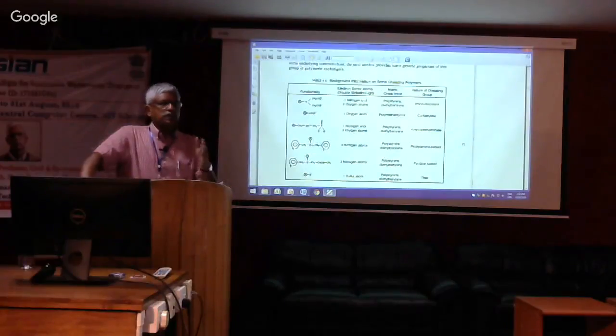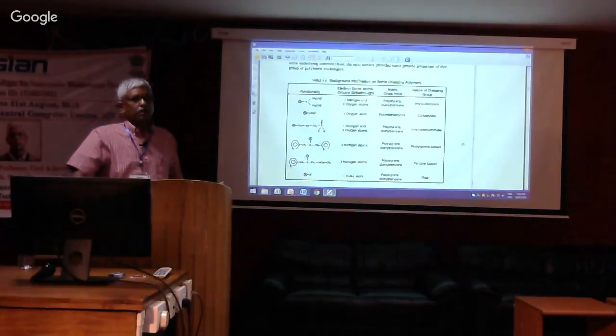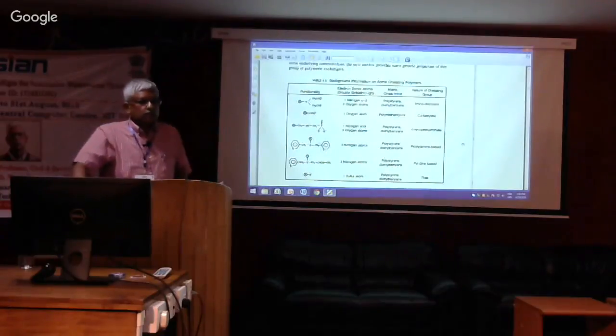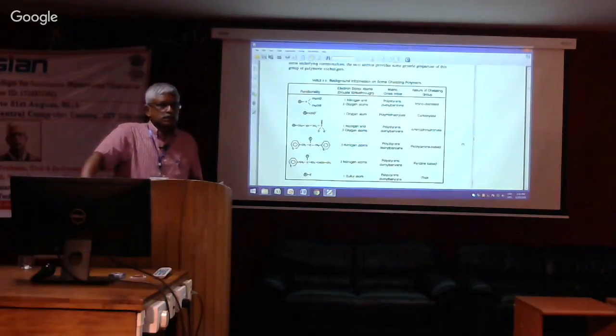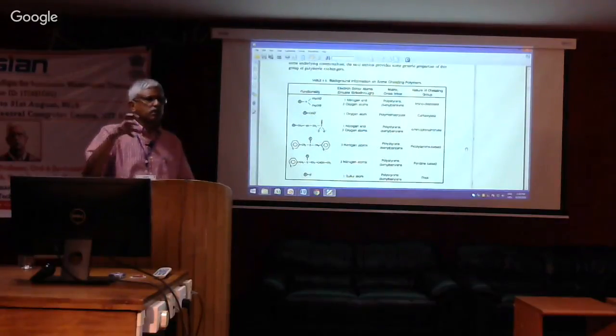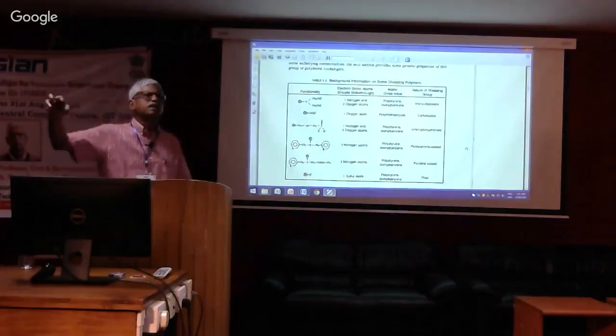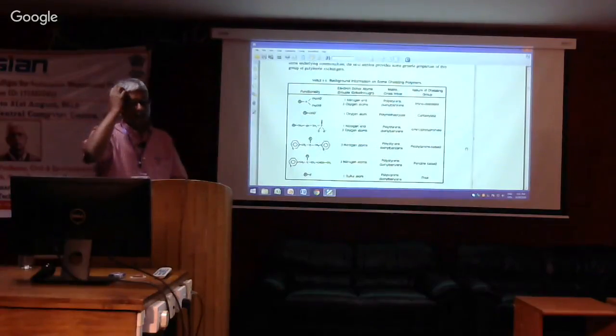Exactly. So, if you have a situation where your site is contaminated and it is a very bad contamination scenario, you have no option. In that case, the whole soil will be excavated, like for 3-4 meters. Well, I shouldn't say the whole soil, it's what we are calling hotspots. The contamination is typically not uniform. You have these zones which are extremely contaminated, so those are the ones that you attack first.